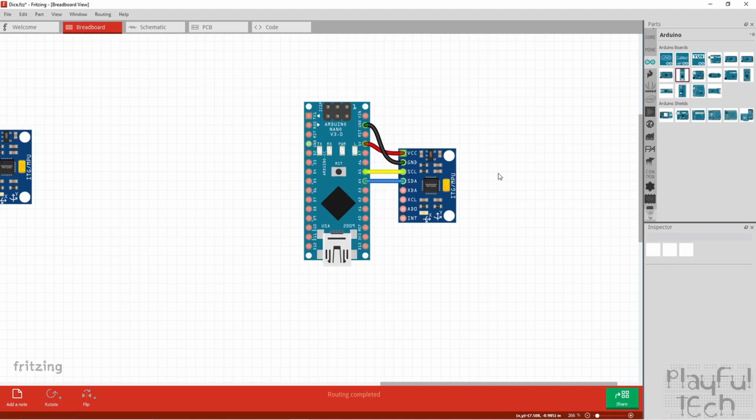And the reason that that's okay is that I2C is what's called an open drain interface. What that means is that the Arduino never actually writes a high signal to these pins when it wants to send data. What it does instead is pull those pins low to ground. So the two states of a wire in an I2C board are either floating or pulled low.